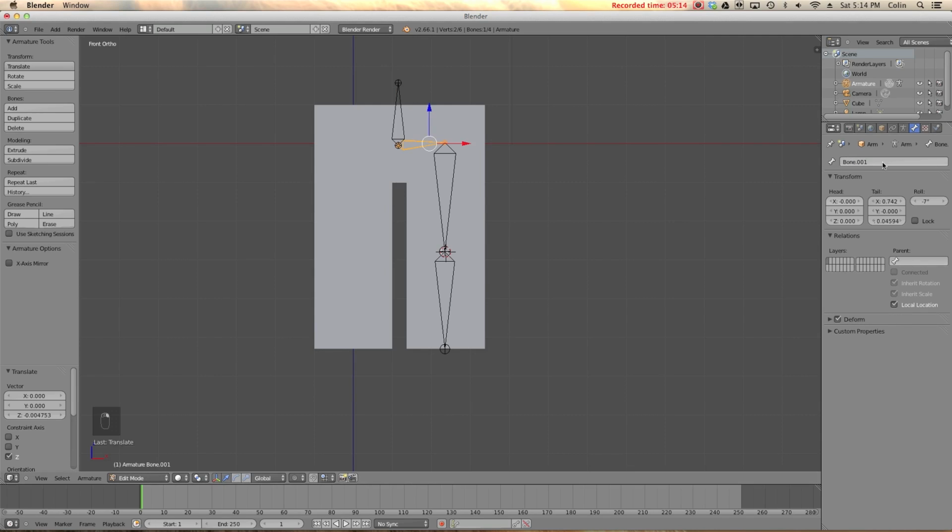And let's select the hip left bone, so we'll call it hip.L. And it's important to name your left bones .L, or capital L, so that Blender knows what you're doing, so it can auto rename them for the right bones. And this will be leg.upper.L and leg.lower.L.